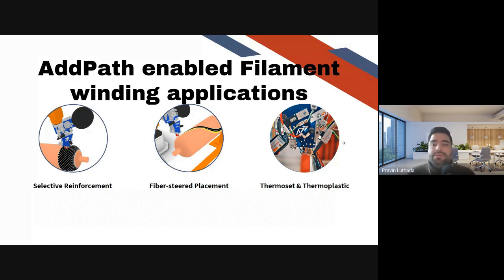It's just bad. So I think what AFP-enabled winding does is basically allow you to shift between materials as your project requires. If it requires you to use more sustainable material that is thermoplastic driven and can be reused, you can very easily shift your processes to be used with not thermoset but thermoplastic or just dry material that will be infused later.